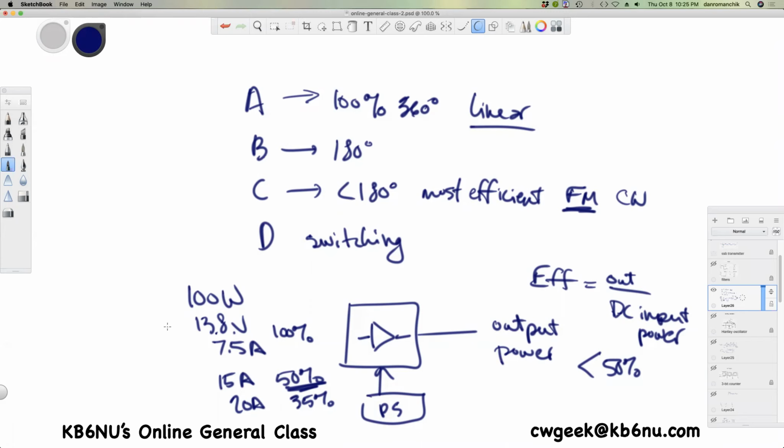final amplifier. And the way you did that was you stuck a piece of wire into a little metal cage where the final amplifier tube was. You stuck this piece of wire in, and what that was doing was just acting as a capacitor, and you were feeding some of that output back into the input out of phase, and that's how you neutralized the final amplifier, that HW101. Fortunately, it wasn't too critical, because if it was real critical, then chances are I wouldn't have been able to do it. But yeah, it worked.